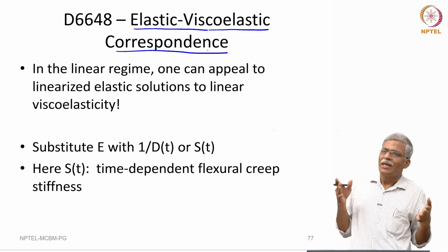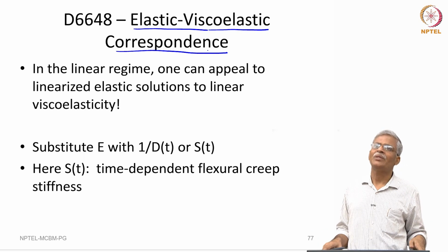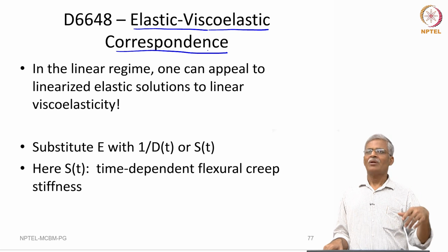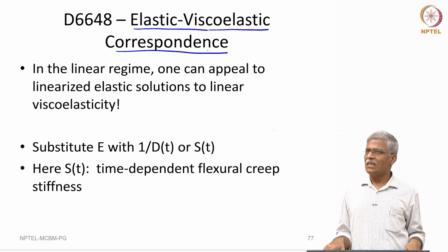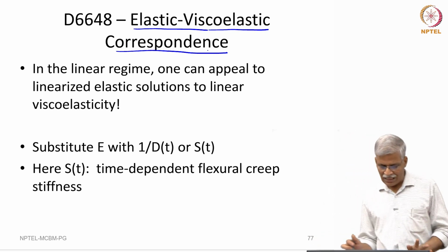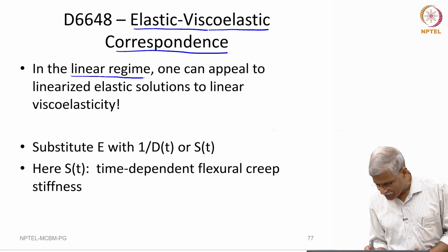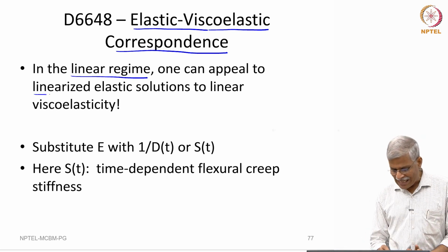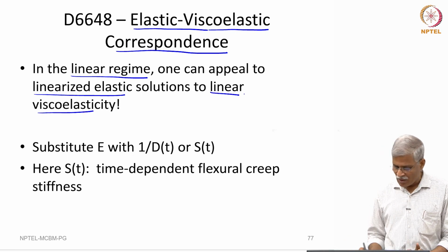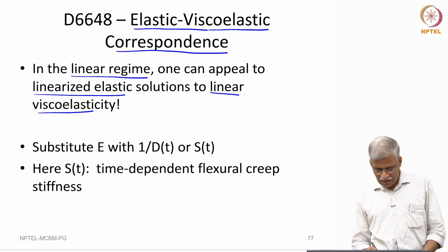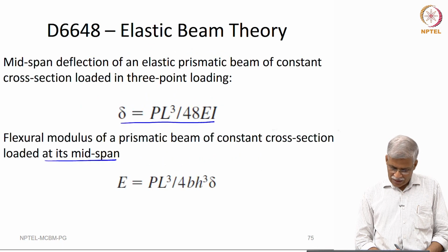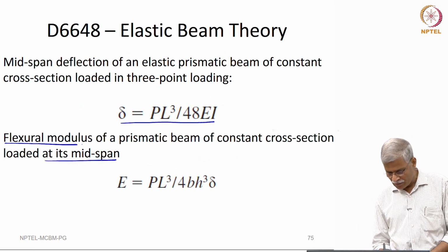There are many criteria, constraints and conditions under which such a transformation is possible, but since that is not part of this particular course, we will not be discussing all these issues here. What we need to be aware of is that in the linear regime, one can appeal to the linearized elastic solution for linear viscoelasticity. So, we will take the value E that was shown earlier, what is really called the flexural modulus, right.